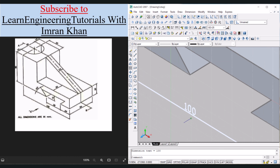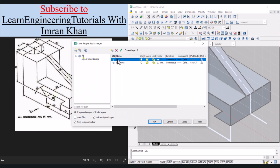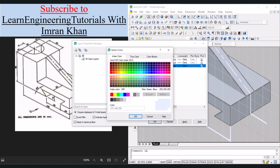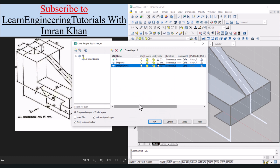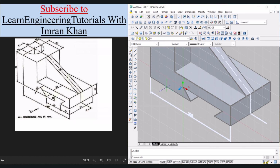We can see 100 value, which is correct. Now let us create a dimension layer for this object. LA enter, click on new layer, rename the layer to dimension, let the color be white, click on OK, and the line weight should be low, so select 0.15 mm, click on OK, click on OK.